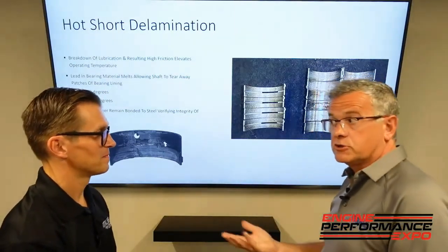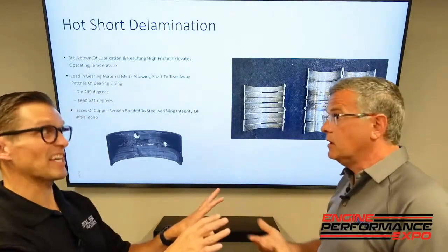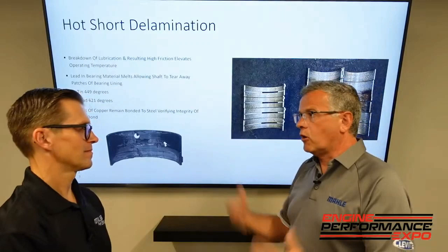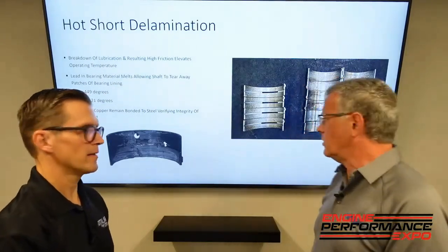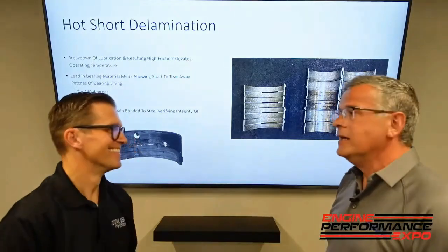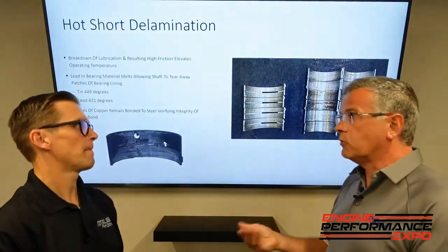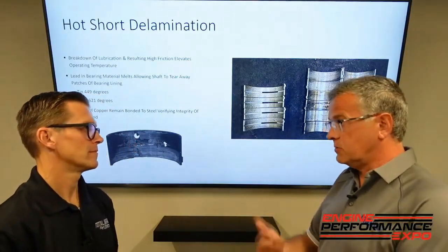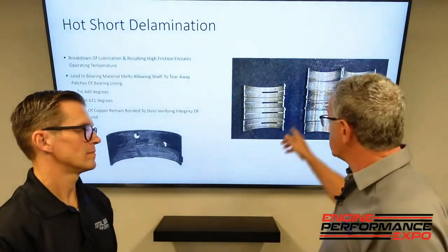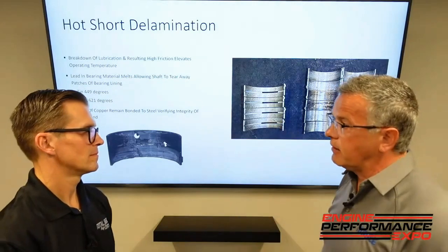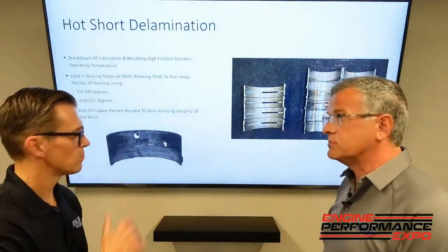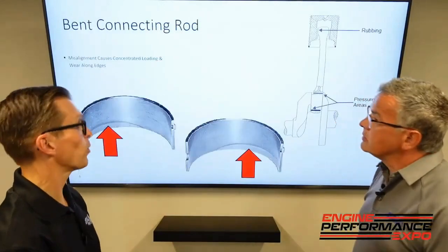Demolition derby cars, I saw some of this happen. Okay, that totally makes sense. They're running and they stop and the engine shuts off. Well, they're already blowing water out. You're running, cranks, you run it again. Dirt late model races, they're running real hard, and they hit the wall, and the engine immediately shuts off, and it's already a higher temperature, and the heat soak can actually melt the overlay on the bearing, and then when you first start up, it adheres to the crank, and it will spin it off. Interesting. It's like micro welding for bearings.